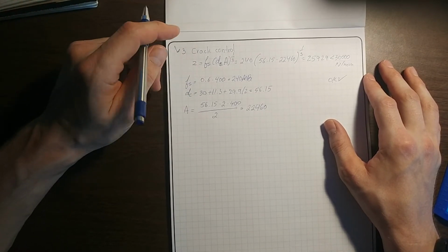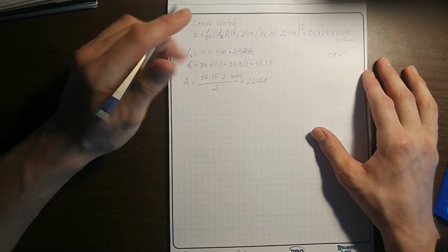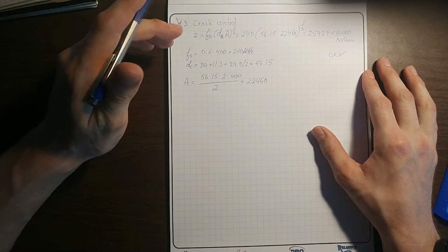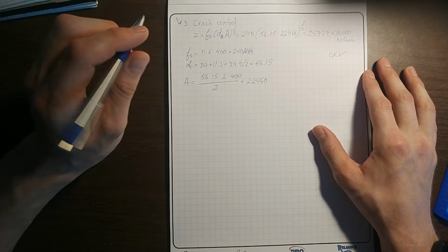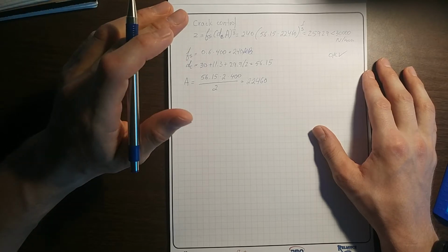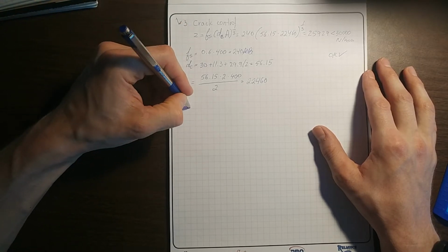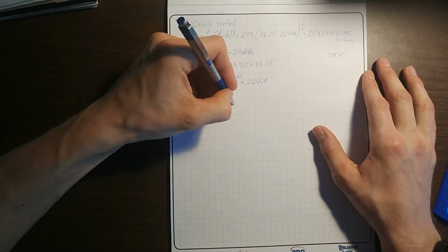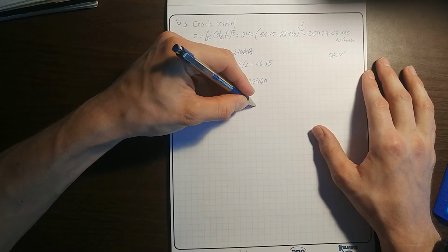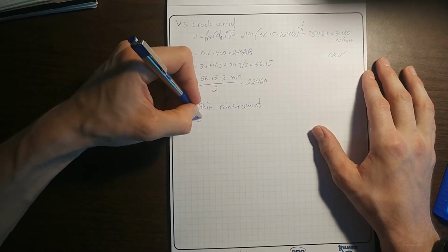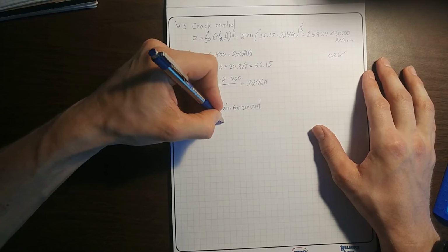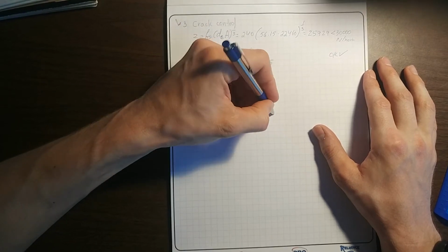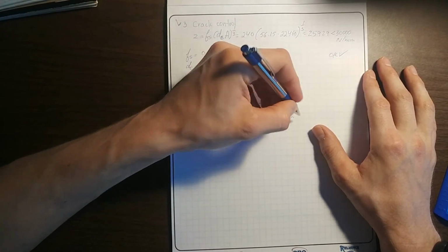the bending moment. As well, it's worth mentioning that if you have a beam with the height over 750 millimeters, you need to do the skin reinforcement check as well. So the fourth check is the skin reinforcement, only for beams over 750 millimeters high.